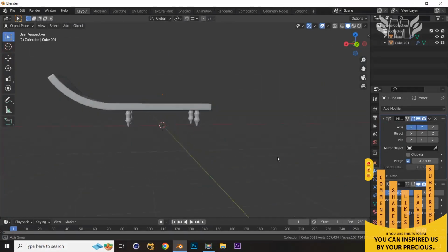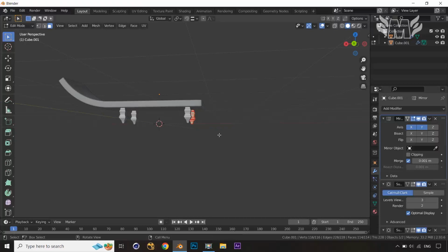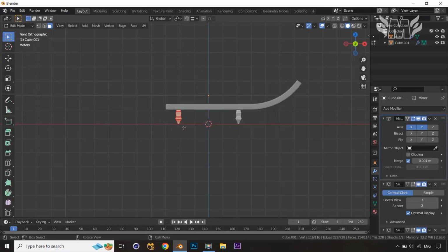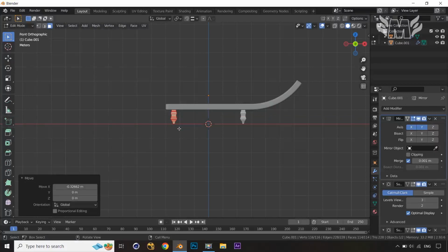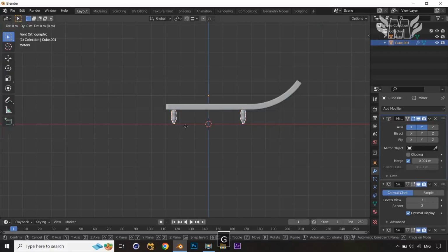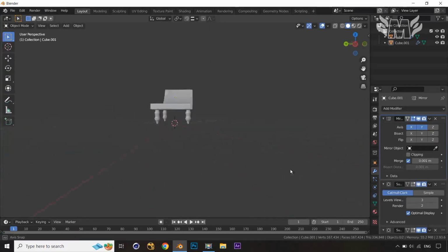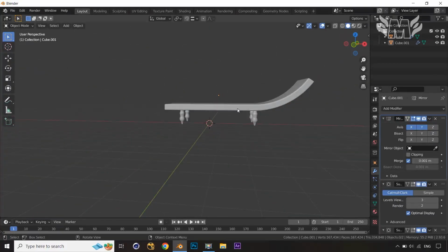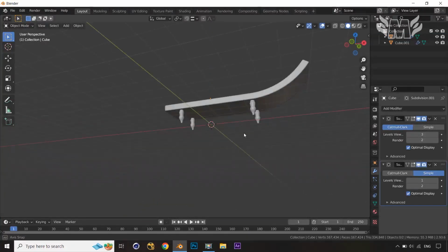Okay, and you can shift these changes also. So what I can do over here, let's jump into the edit mode, jump into the front view, and press G and move a little bit into the x-axis, so I can shift it something like this way. Then press Tab again, select this one, press G and the x-axis, and let us take it something like back over here, so it will be settled properly as we require. And you can take it a little bit lower also, so G and Z, something like this one. So now it looks better to us.